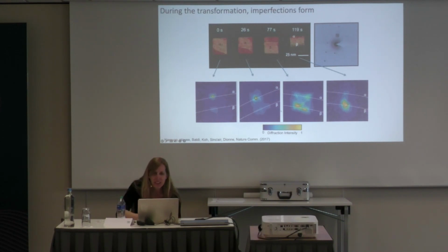So great question that led perfectly into this slide. You definitely are getting the lattice expansion. The interesting thing is you probably know that the diffraction peak full width at half max basically corresponds, in a way, to the purity of the crystal. So you can see this broad full width at half max here.